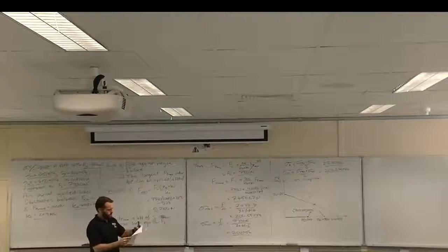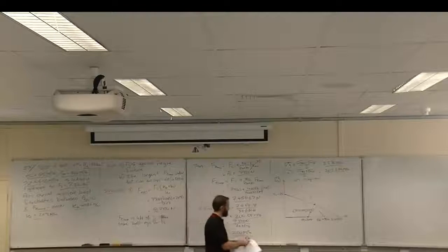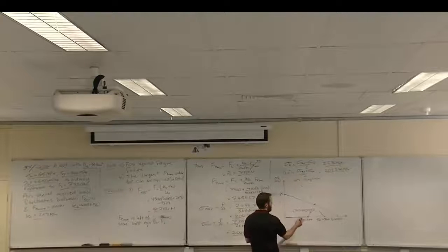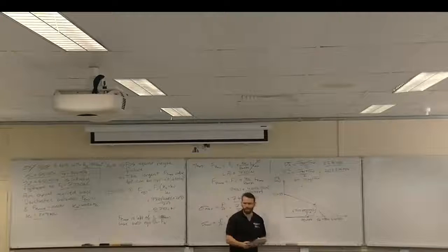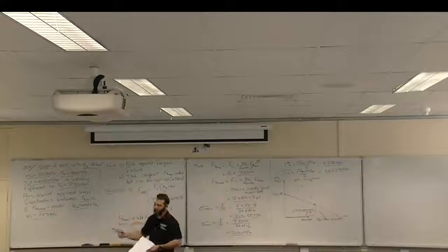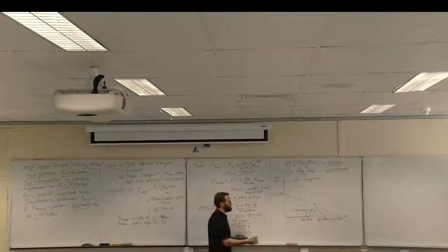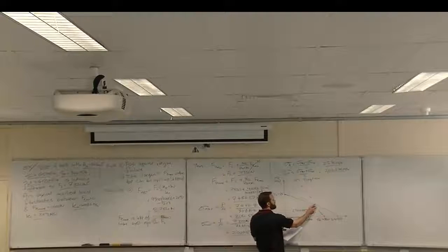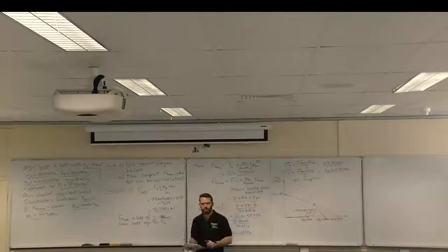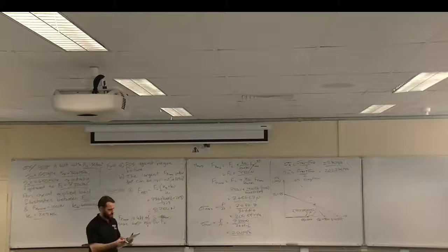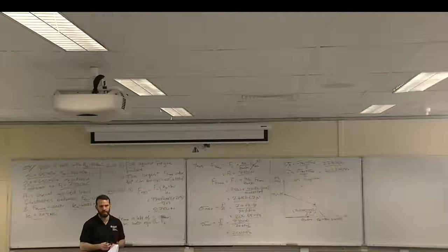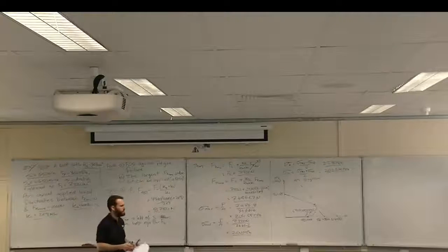Cool. All right. So we're going to do a few things. Effectively, we want to know this ratio to this ratio to answer A, and then for B, we want to know what the actual force is at that point. So our job is to work out that intercept, and that intercept could be with the Goodman line and it could be with the yield line.